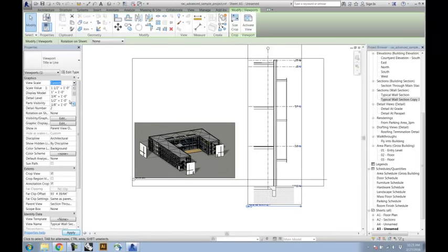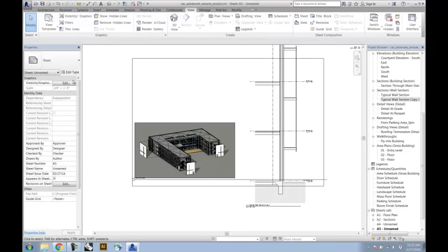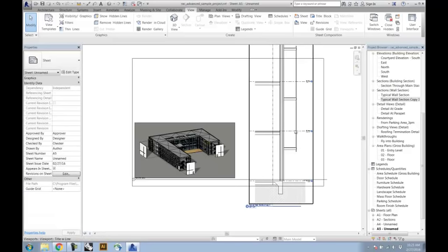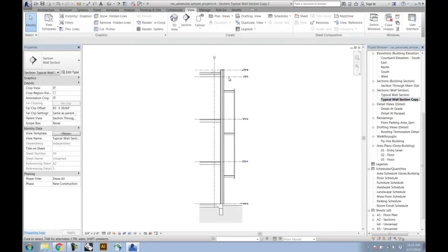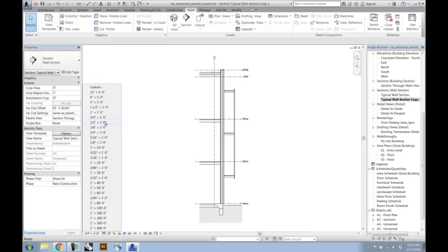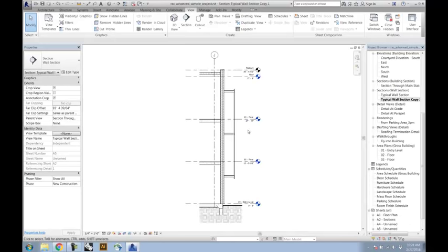So if I want to go to, like, 3/4 of an inch equals a foot, that's pretty big. I can additionally come in, you can adjust the scale there, or you can do it here under the actual drawing. You can see how these things match each other. Let's see if 3/4 is too big. Let's just try 1/4 inch equals a foot.